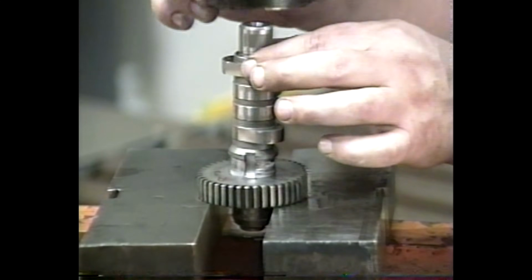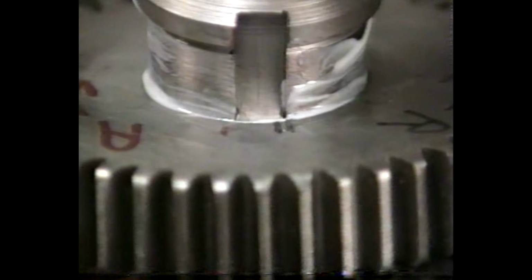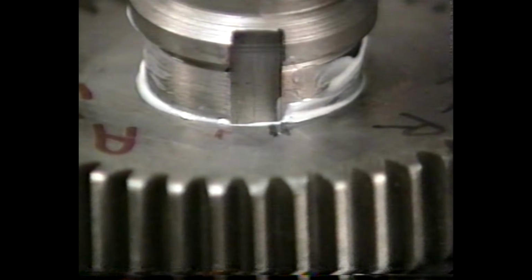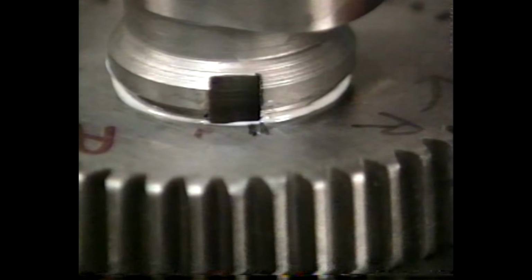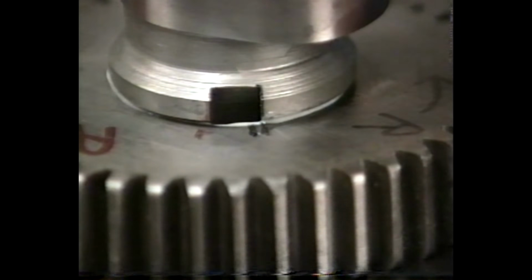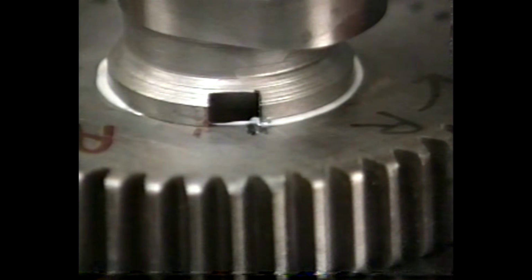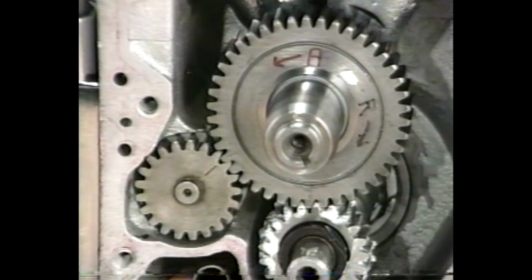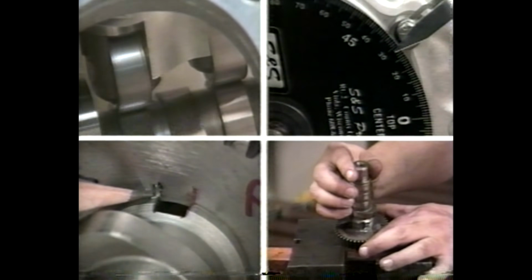With the camshaft straight and turned to its new position, we gently press the shaft back into the cam gear until the gear sits firmly against the shoulder of the camshaft. If by chance the camshaft twists and moves out of alignment with its new position in the drive gear, we must press the camshaft out again and repeat the correction procedure. Once we have the camshaft reassembled, we replace the cam in our engine. We then repeat the degreeing measurement to confirm our calculations and to prove that we have indeed retarded our valve timing by 2 degrees. We may have to repeat this entire procedure a few times until we achieve the desired cam timing.